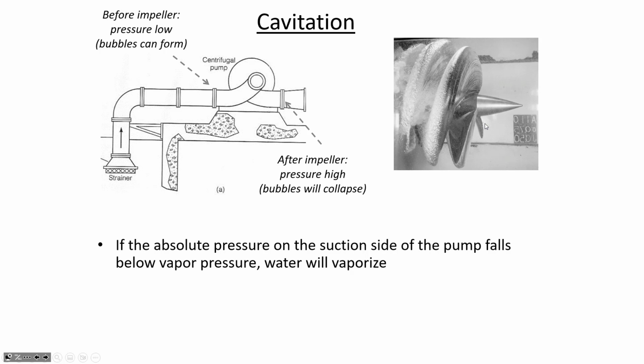And if the blades get eroded and it's imbalanced, it can start to vibrate. And there have been big industrial accidents. There was a notable one in Russia in, I think, 2006. They had a big hydroelectric facility that basically exploded because one of the impellers at this hydroelectric facility that was supposed to be generating electricity, there was some cavitation that occurred. It got out of balance and it just started to wobble until basically the entire building that this impeller was in got completely destroyed.